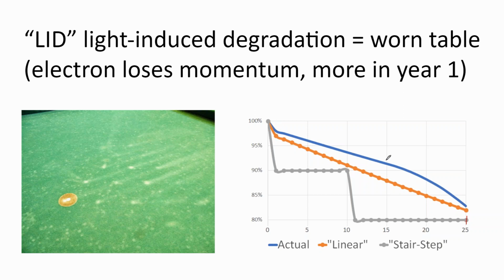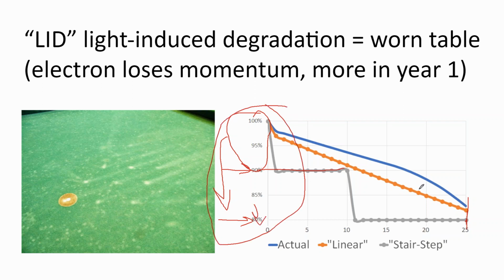So for the warranties, it's a 25-year warranty. There are a couple of different warranties. A very standard one is a 10-year warranty at 90%, and then a 25-year warranty at 80%. And so what that's saying is we're going to warrant 10% loss. If you go beyond a 10% loss in the first 10 years, it'll trigger the warranty. And then it becomes if you lose more than 20% before year 25, it'll trigger the warranty.